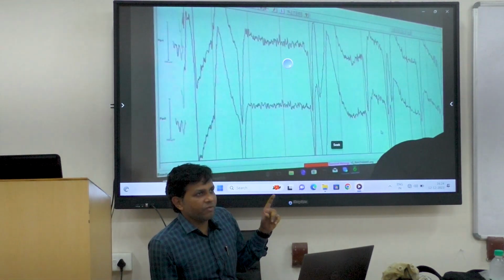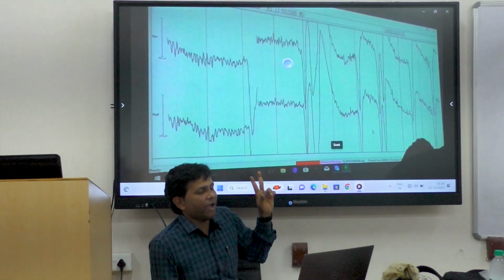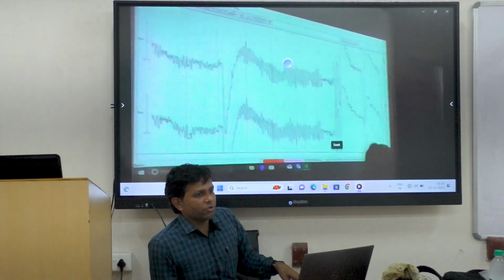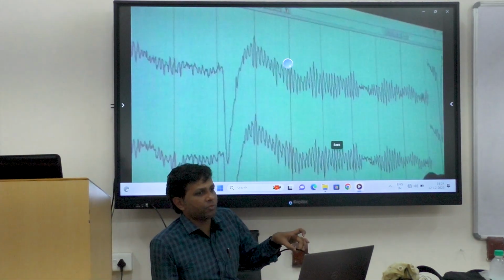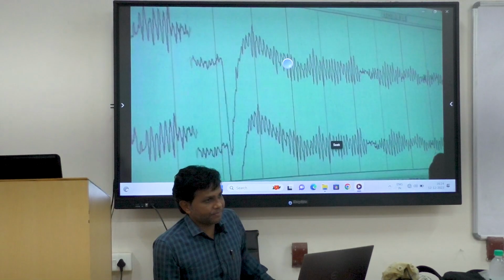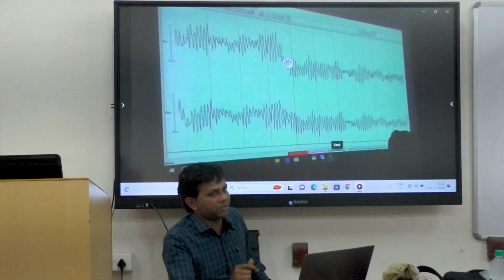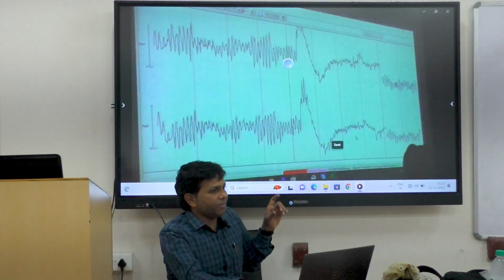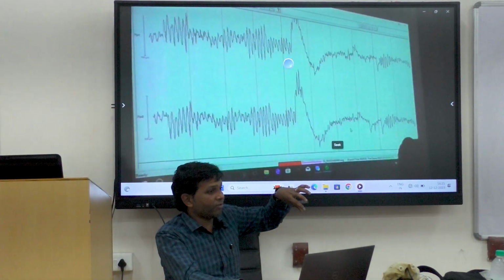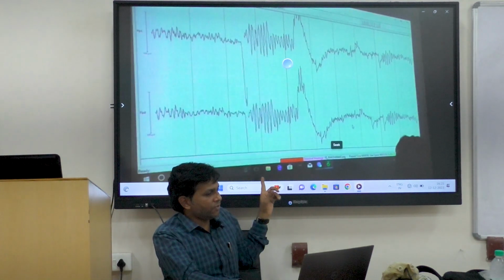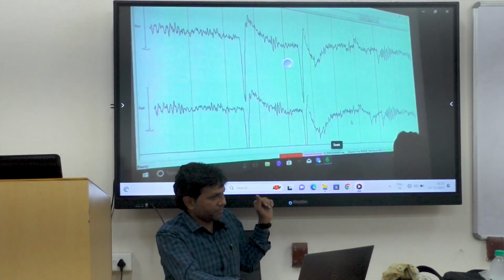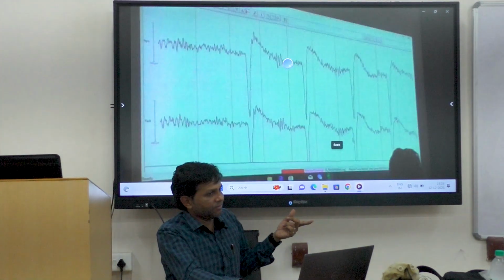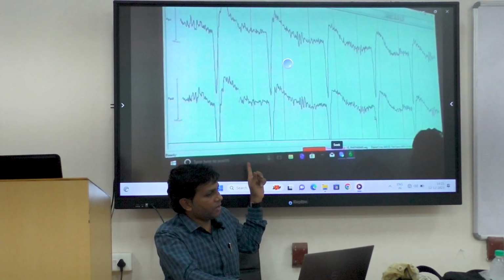During data acquisition, normally we should not switch on the light and fan. Even the AC we should switch off. Even the laptop should not run on continuous power supply, you should run it on battery. That also creates artifacts, noise. Now as I mentioned in the beginning, trial 1, trial 2, you ignore some first 5 trials or something like that, right? Over time the subject stabilizes, his cognitive thinking stabilizes, then you record the brain signals. See how we are going to record.